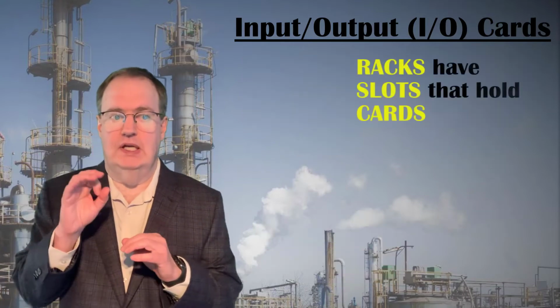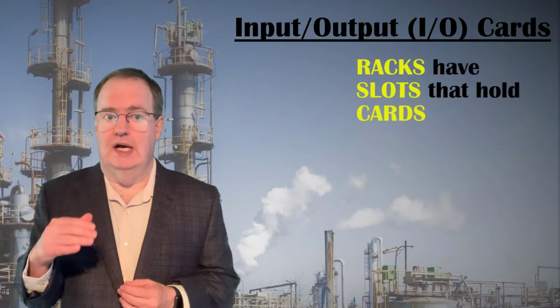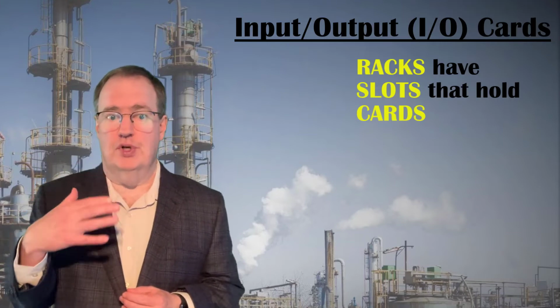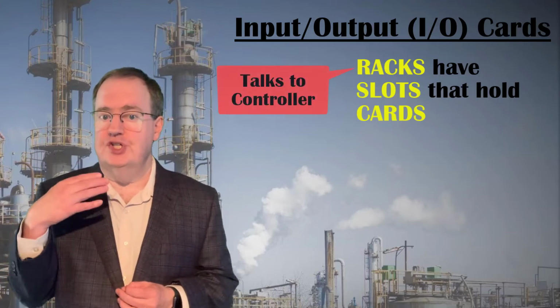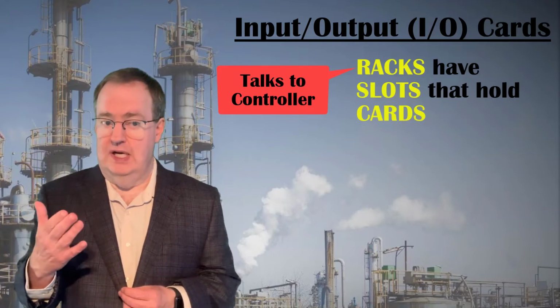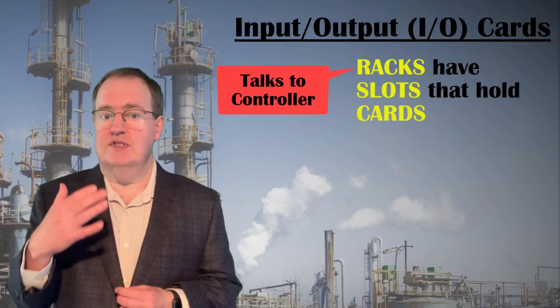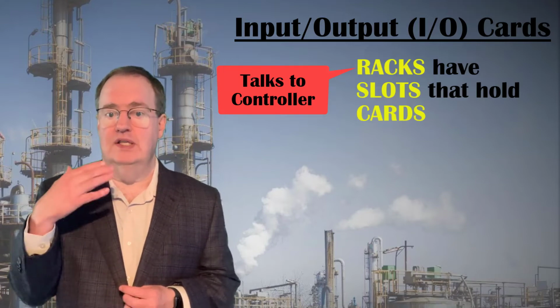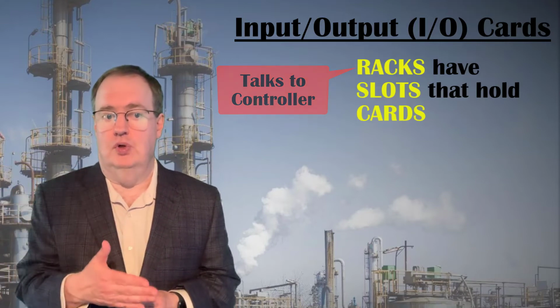I/O cards fit into slots in an I/O rack. A rack generally has 4 to 12 slots, one of which is used for the Ethernet switch that has an IPv4 address and sends and receives thousands of signals per second via the Ethernet ring to its controller.